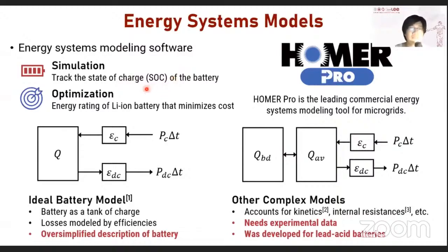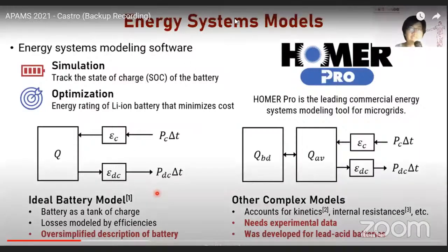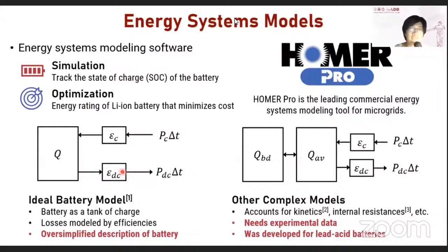Second is to optimize the battery by determining its energy rating or its size that minimizes the cost of generating electricity. To do this, the energy models will typically use an idealized battery model. Here we model the battery as a tank of charge, whereas energy losses are captured by efficiency parameters.